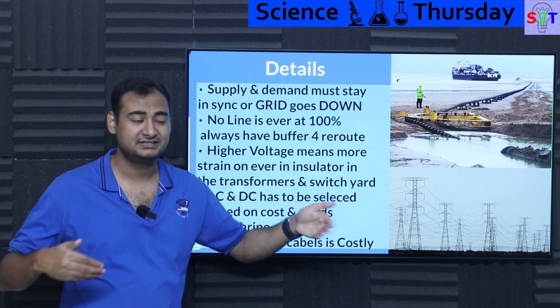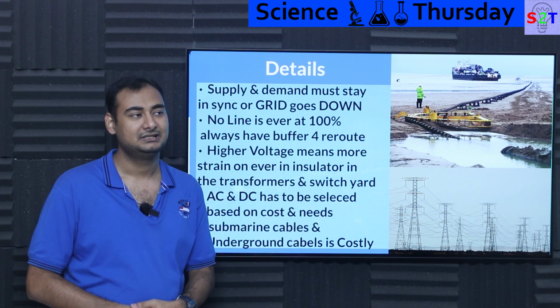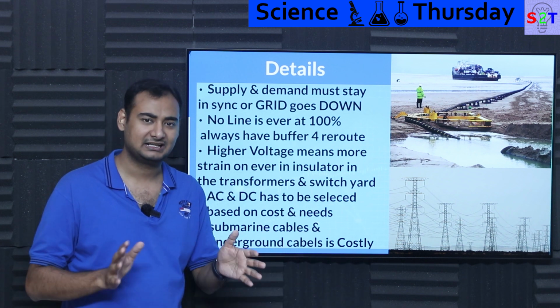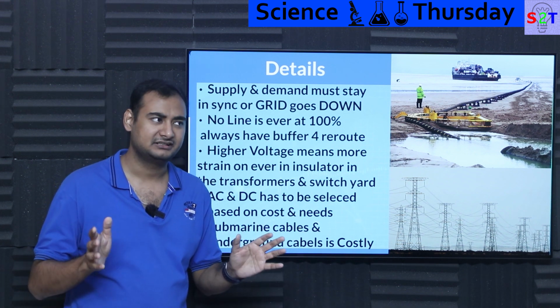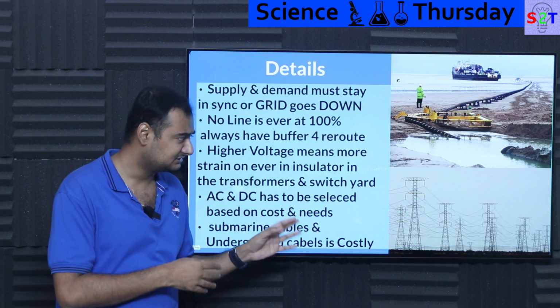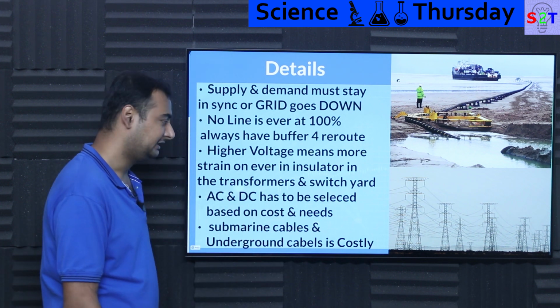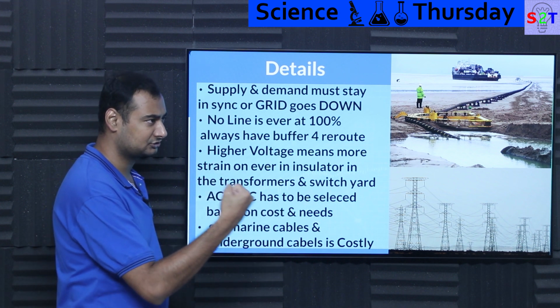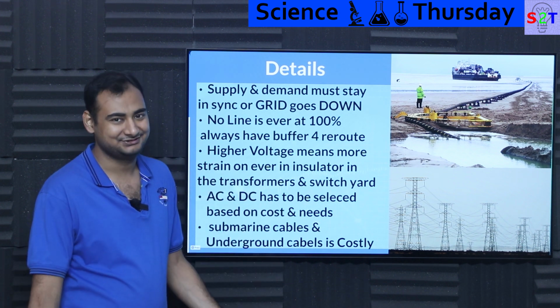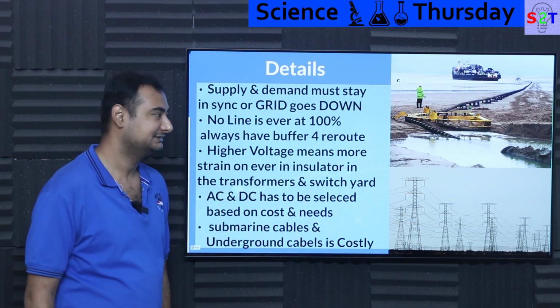That's why, for long distance, you cannot transmit AC power, as in hundreds of kilometers. The moment you are at 100, 300, people say generally at 300 kilometers, it starts to make more sense to use DC. And if you are going underwater, 80 kilometers is the dead limit. And if you are like China, you want the Three Gorges 12 gigawatt power transmission, you have to use DC. You can't transmit it through AC.